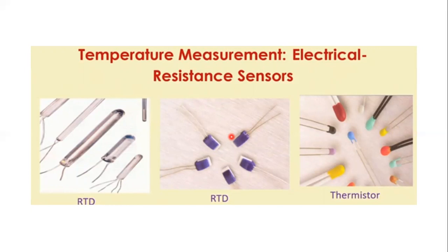We have studied the thermocouples, and another one is RTD, which is constructed using metals, and metals have a property that their resistance increases with the increase in temperature. And the other one is thermistor. The resistance of semiconductor materials generally decreases with the increase in temperature. So thermosensitive resistors like semiconductors provide a negative temperature characteristic. So it is also known as NTC thermistors, negative temperature coefficient thermistors.